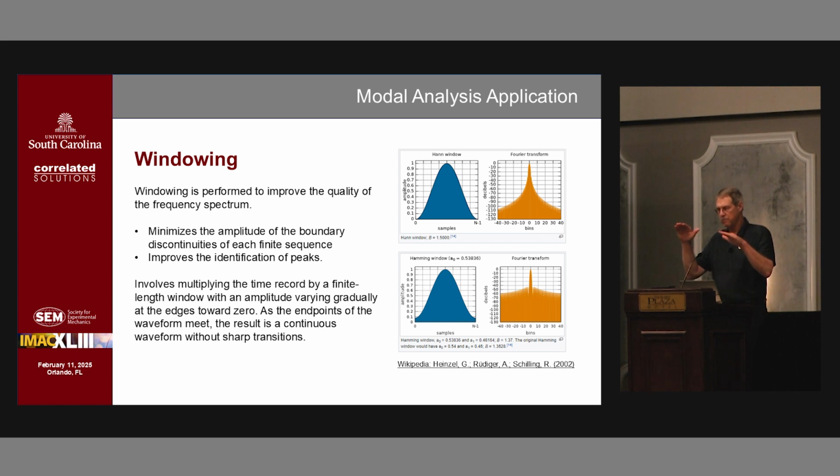If one end of the hammer moves slightly, you can see that this end starts at 0, this end moves, and you have a difference in displacement, from 0 to something over here: rigid body translation. The filters are very important to smooth that out and flatten it to be 0 on both ends. We've learned quickly that you need to use that in this case, unless you're certain that both ends are stable at 0 and the rigid body end, or whatever component you think is stable, is really not moving. So for displacements, the windowing functions become important.